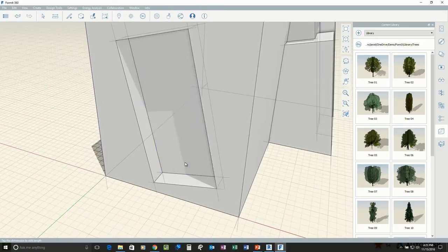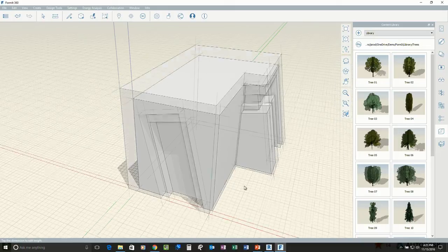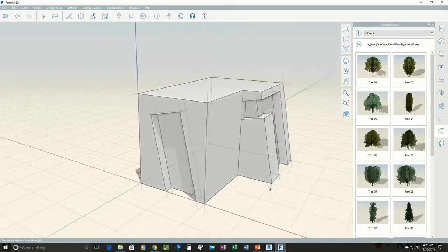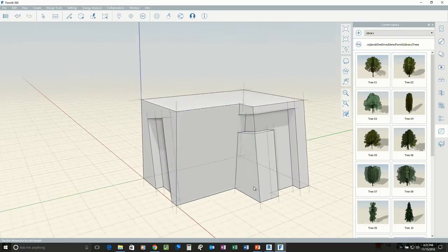Here's a wonderful trick, by the way. If I want to take this and push it all the way down, I don't have to build something else to subtract or whatever. I can just pick this surface and push it all the way down. It just instantly subtracts. I love that. Someone from a design standpoint using SketchUp might think extra about that, and it's like, no, just pick on the surface, just push it down. You're done. Okay? So very quickly, just laying this out.